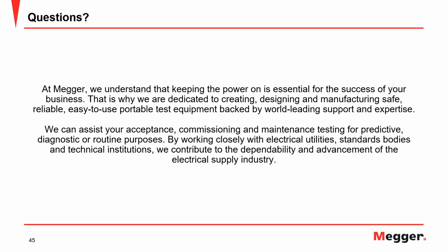If you have a typical Y or delta connection, 3-phase, then of course you're shorting 3 or maybe 4 bushings together. If you don't short circuit the bushings, and they probably are, because it's a step in the preparation detail you want to attend to do a power factor measurement anyway, and so then presumably you're going on to test the bushings.